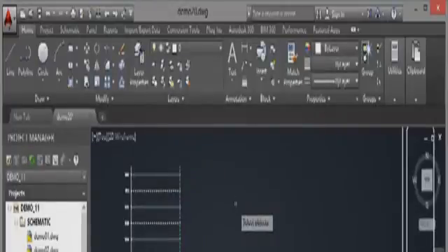So I'm just going to hit Escape there and go back to Stretch again. And then you just do a quick click and then drag, okay? Don't hold the mouse button down, otherwise it does that lasso thing. Do a regular stretch using a rectangular crossing window. Remember, stretch only works with a crossing window, crossing polygon, or, as we saw, a crossing lasso now as well. So when I click there like that, it selects that entire right-hand half of the ladder plus the rungs. Now, we want the rungs to stretch across to the right. The wire, the vertical one, will just stay where it is and move in the plane of the stretch. So I just press enter to confirm.